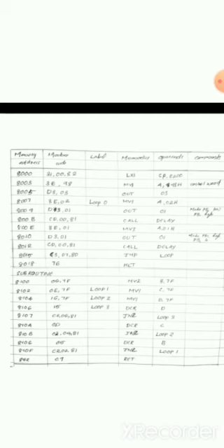RET (return) is executed next, and control returns to the main program. Next, 0F is loaded in the accumulator and sent to port C. Now PC0 to PC3 carry low voltage and PC4 to PC7 carry high voltage, so the green LED shines.